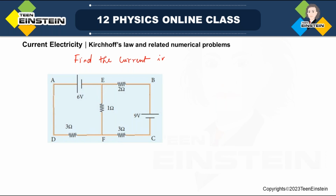Current in each branch. What is a branch? We had discussed that day. A branch is actually a portion of the circuit between two junctions. Suppose here is one junction, here is another junction, so this is a branch. Similarly, A, F and C, these are two junction points, and so resistor 3 is actually a branch. Like that. So we have to find out the current in each branch.